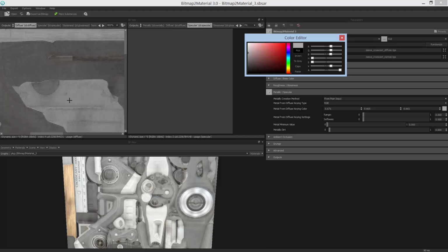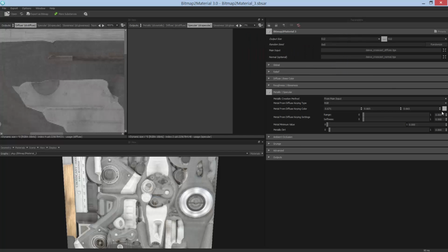So here what we're doing again, like I said, is looking for this metal reflectance value. This is going to be in a range of around 70 to 100% specular for an actual polished, smoothed, or raw metal, we'll say. And so for that, I'm picking this value, and we're going to use this as our key color. Here we need to be careful over the color value that we're selecting in this diffuse map. Traditional diffuse textures were not authored to be physically correct, so the value we choose for metal in the diffuse texture needs to be a value that is at least 60 to 70% specular.